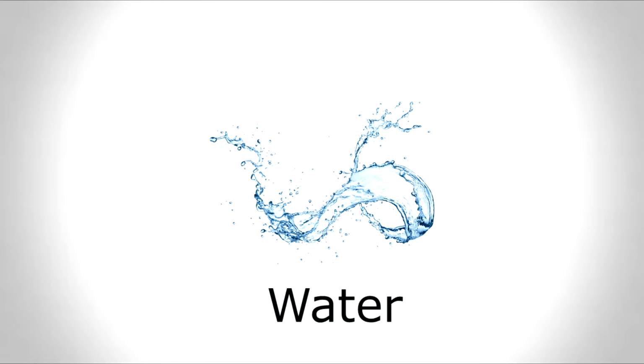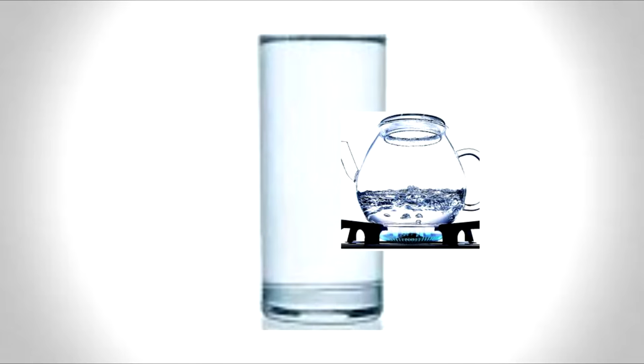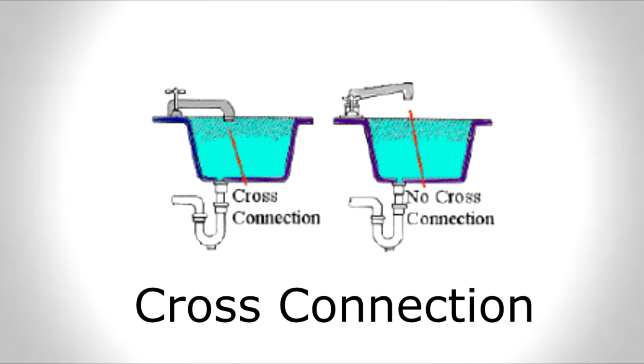Let's talk about water inside of a retail food establishment. Water inside a retail food establishment must be potable. Potable water is water safe for drinking and cooking. A physical link between dirty water and safe drinking water and a plumbing system is called a cross-connection. Cross-connections should be avoided at all times.